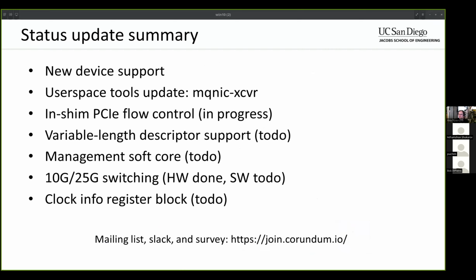The only thing I haven't pushed yet is, I think, the 100 gig design for the Stratix 10 DX, because that one doesn't build yet due to some issue we're trying to figure out on the Intel forums. Everything else is up, but on the Stratix 10 DX and the Agilex, everything with the E-tile, the PTP support doesn't quite work right yet. So that's a to-do to fix at some point.